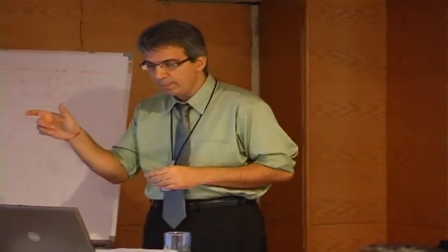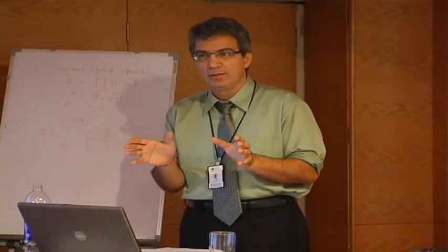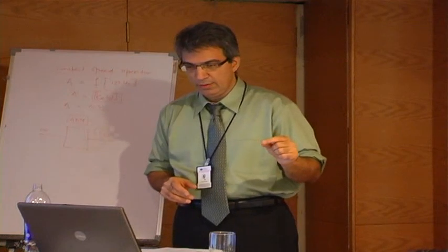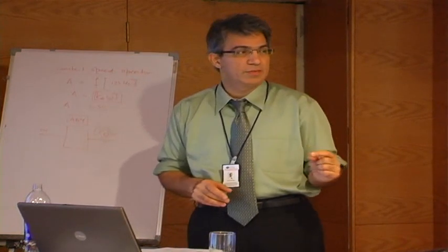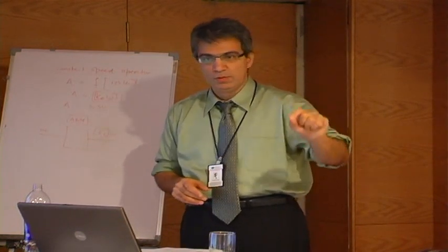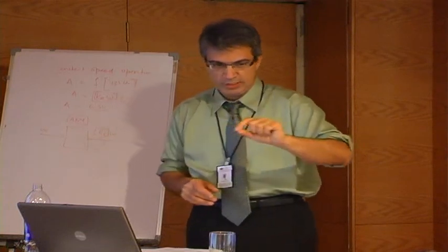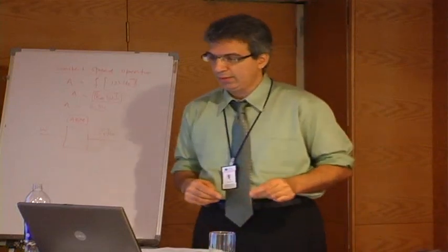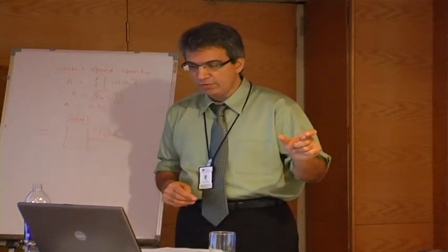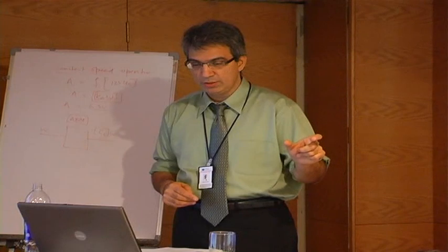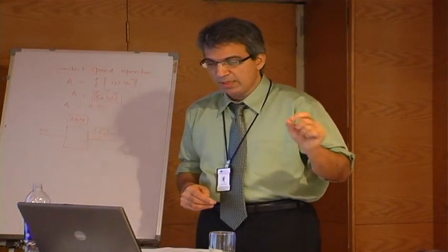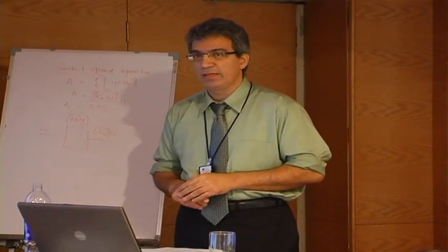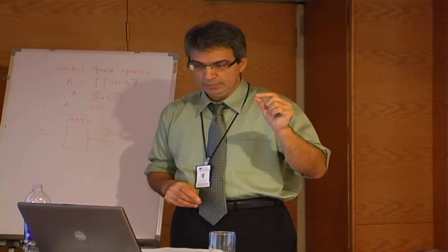So, the parameter file: a single text file which is included in the simulation. It includes all parameters of interest, so it allows you to say, okay, this is what I'm going to change. Anything you want to change, you put it in the parameter file. It's a convenient way to organize your design and important parameters, and a convenient way to change parameters and read on analysis. That's the importance of the parameter file.